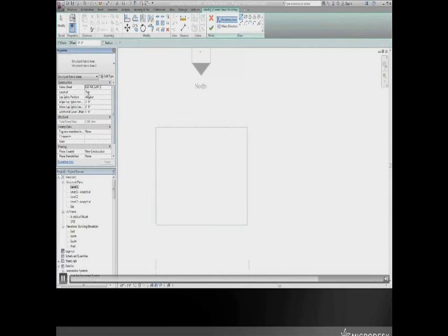And here you can choose what type of fabric sheet you're intending to use, your major and minor splices, and so on. So I'm just going to choose a sheet here and just draw it into my slab. I'm going to lock it to my slab area so that if my slab was to change shape, the reinforcement will change with it.